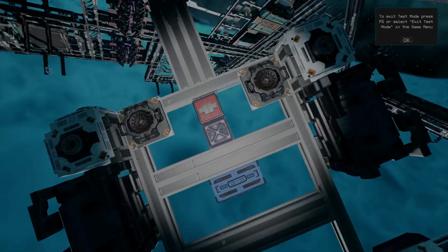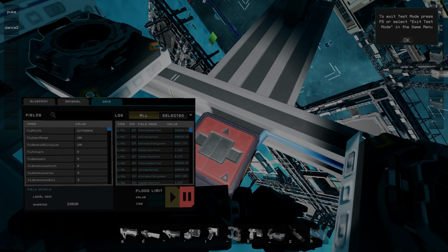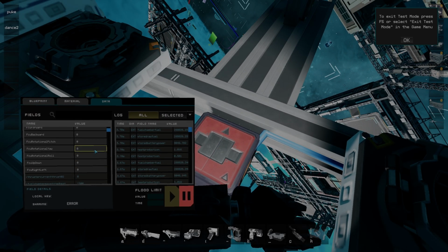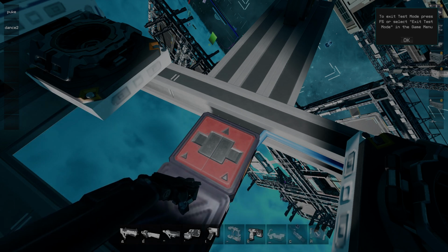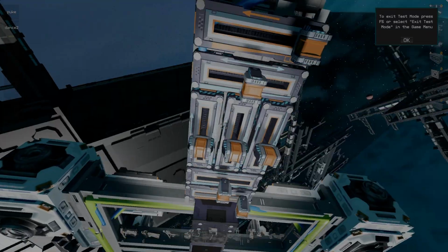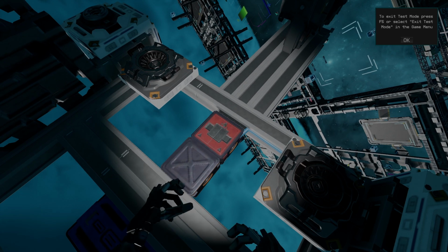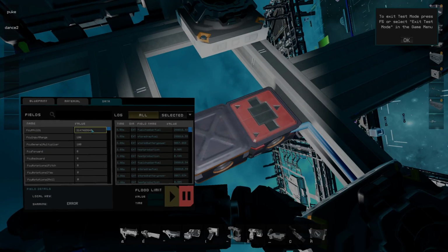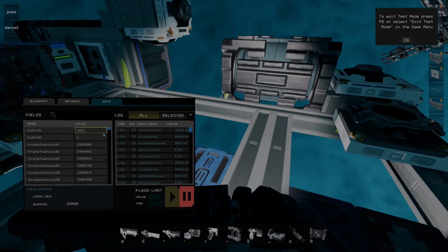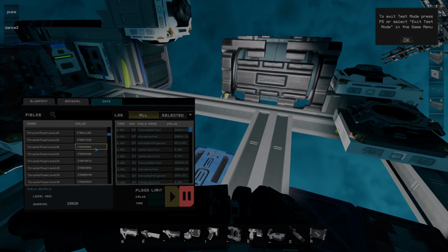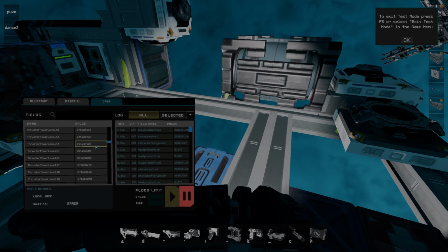Those levers send their information to that red little box. This is called the controller. The controller is reading all of the values of all of the levers, such as the FC rotational yaw that you've just seen me use right now. The controller isn't the one that's moving all of your different thrusters. That is the work of the flight computer, which is the blue box. The flight computer will manage up to 50 different groups of thrusters.